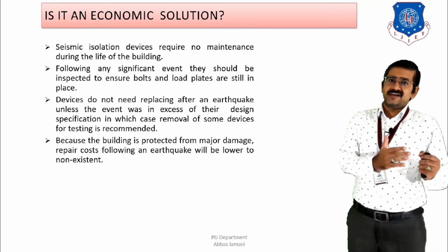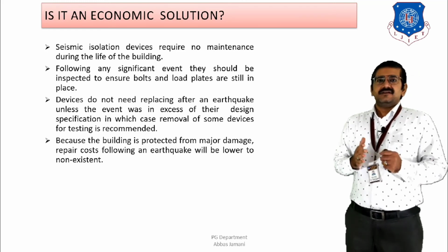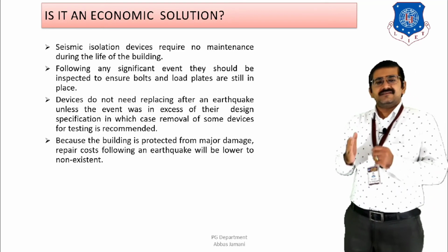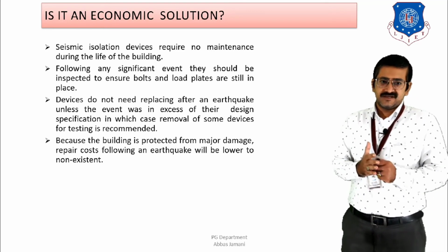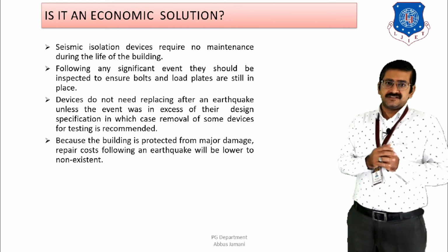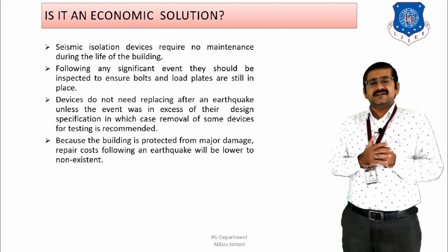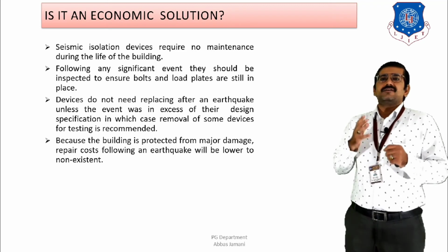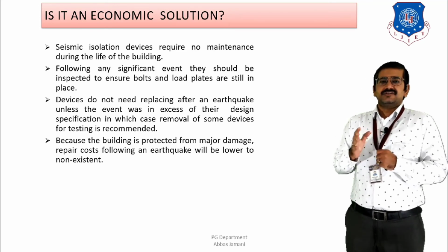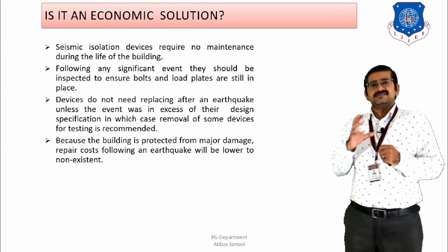So the same thing applies to the dampers also, where in case of dampers we can safely say that once the damper is installed, the maintenance is going to be on the minimum side, right? So as a result of that, no maintenance will be required during the life of the structure. Even after the shaking of the earthquake has taken place, only the position of the bolts and the plates needs to be checked, so that the function of the damper is not changing.